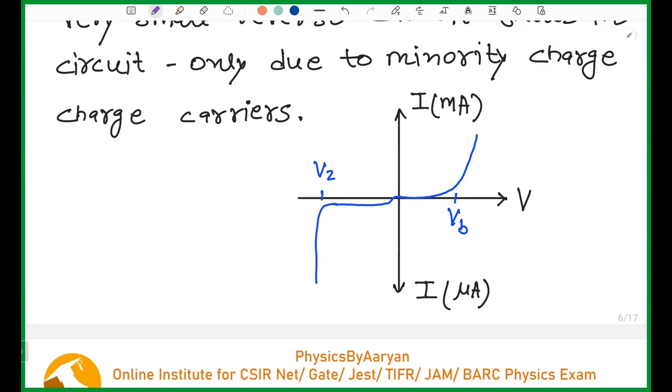Excuse me, sir, I had a doubt. In forward bias, it can stop up to 0.7 volt, right? Until 0.7 volt the current will be very small, and after crossing that barrier, the current keeps flowing. So compared to this, how much reverse voltage can it block? Will it be 10 volt, 20 volt? How much voltage can it block at maximum?